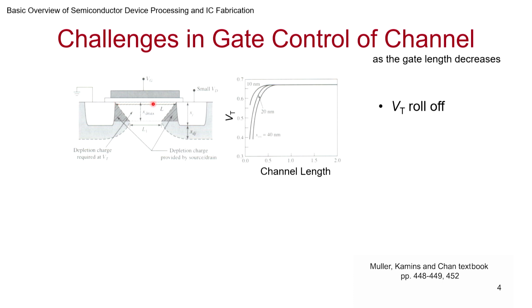And right under the gate, very close to the gates, that is the oxide silicon interface, you will be able to invert it, deplete it, or accumulate it. So you can make it more p-type, make it depleted, or make it more n-type. So you can do that by controlling the gate. And that is the whole game of controlling this transistor.